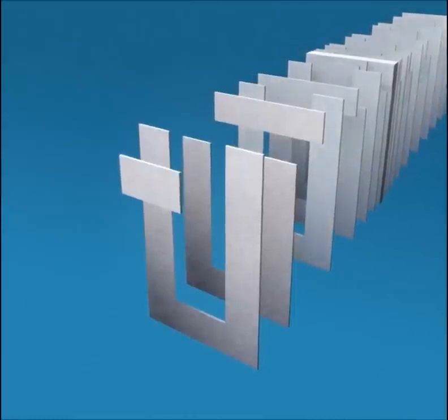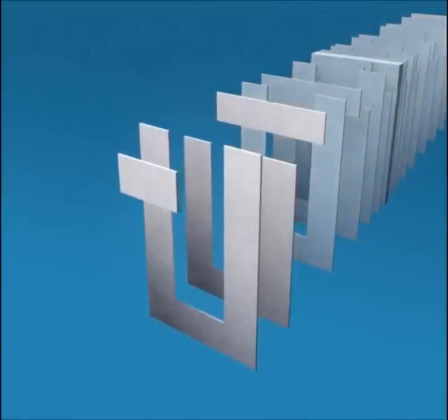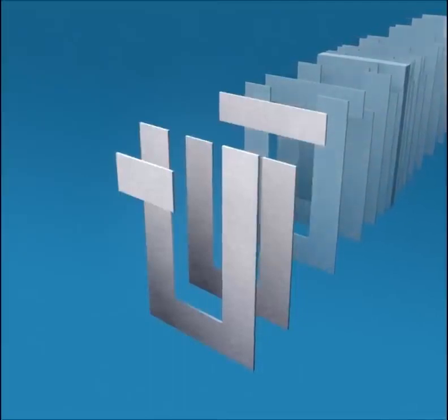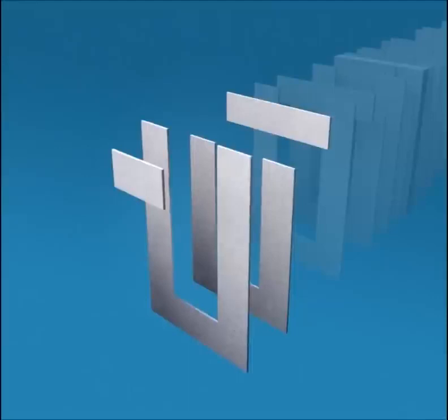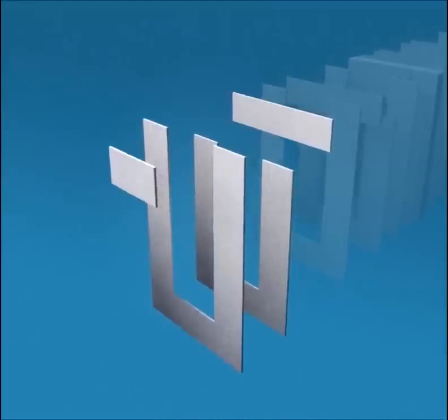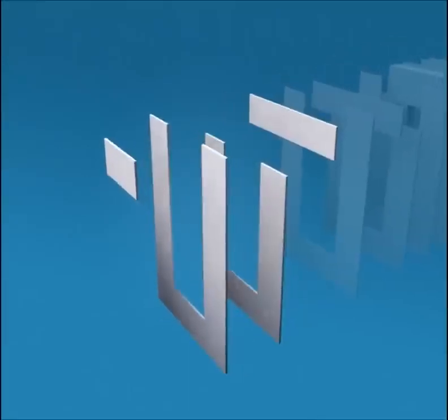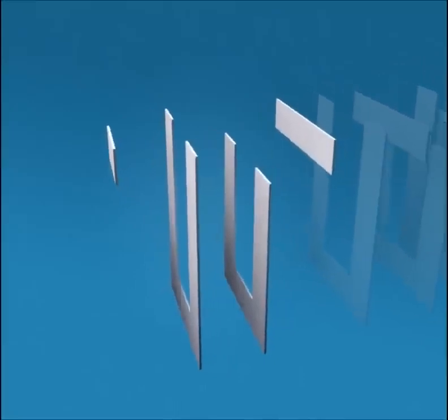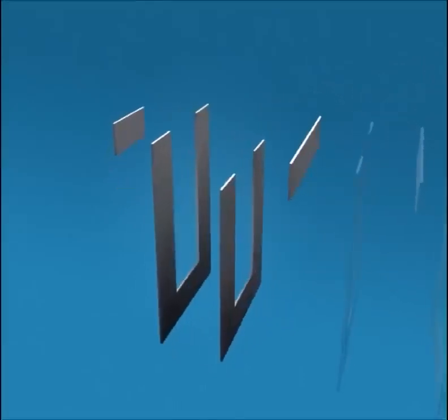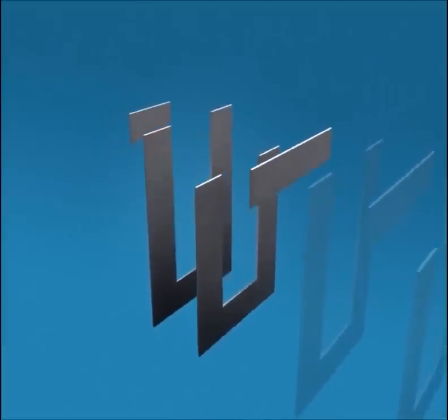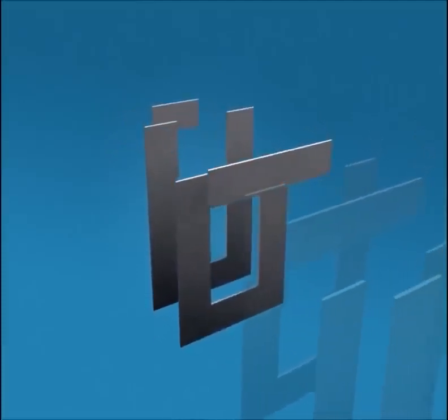The core is used to provide a low reluctance path to the magnetic flux, but it is also subjected to circulating electric currents. These circulating currents, called eddy currents, produce heating and energy losses within the core, resulting in decreased transformer efficiency.